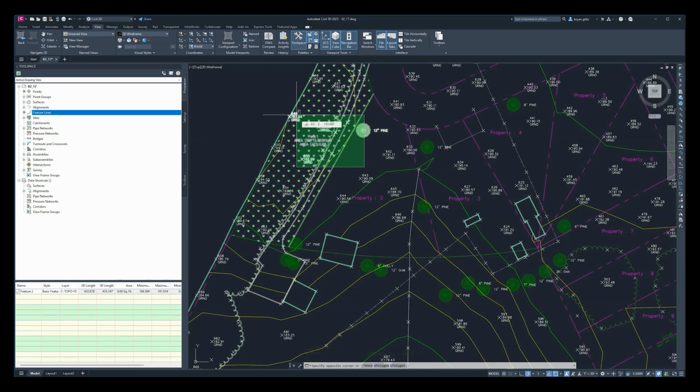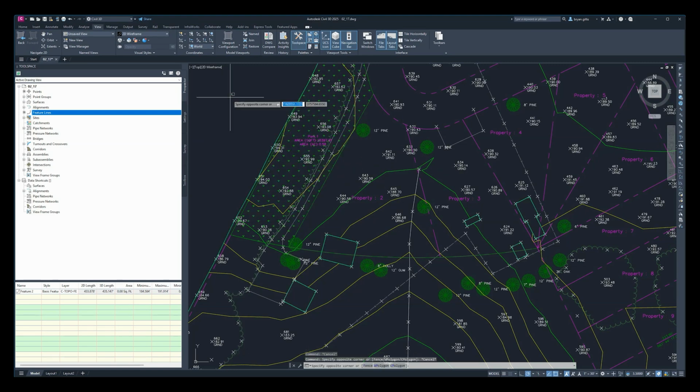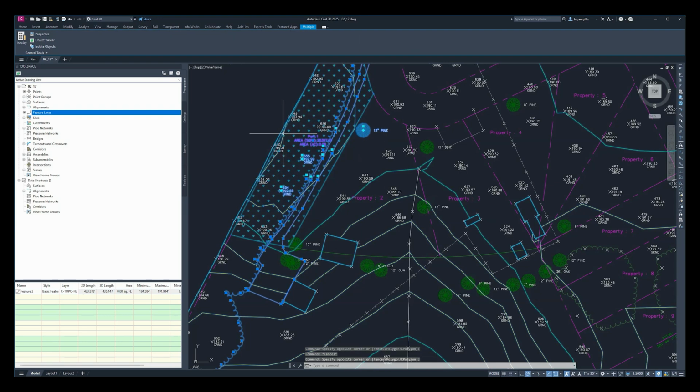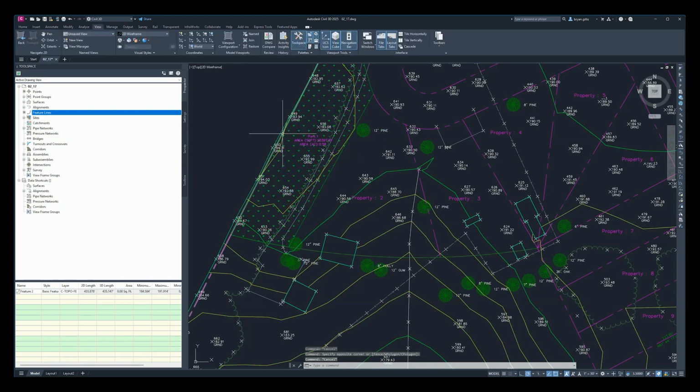And when it's selecting this direction, it's going to select anything it intersects. So that's the difference. Selecting to the right is a completely within selection method, and selecting to the left is an intersects selection method. I just want to share that bit of information in case that wasn't made clear previously, because I know at times I can go kind of fast.